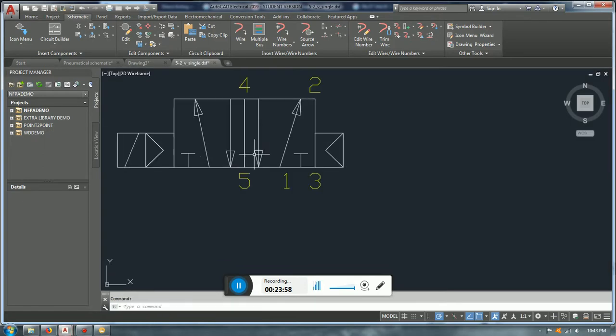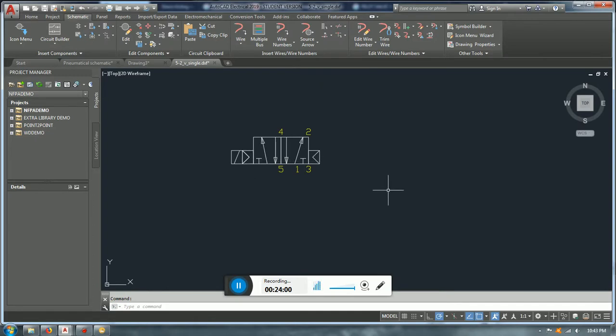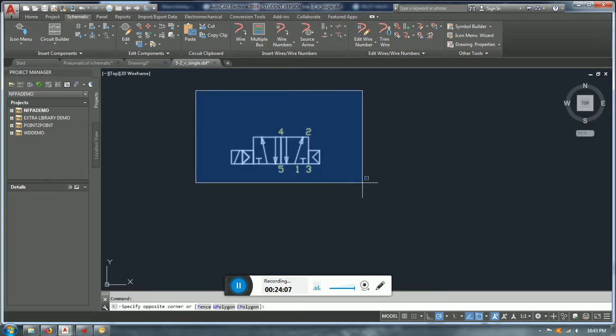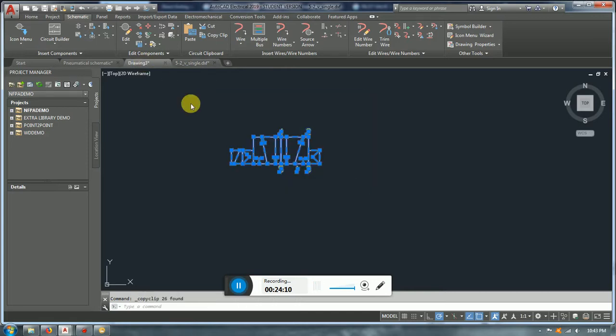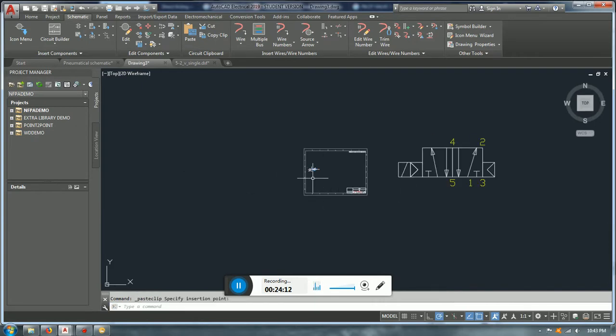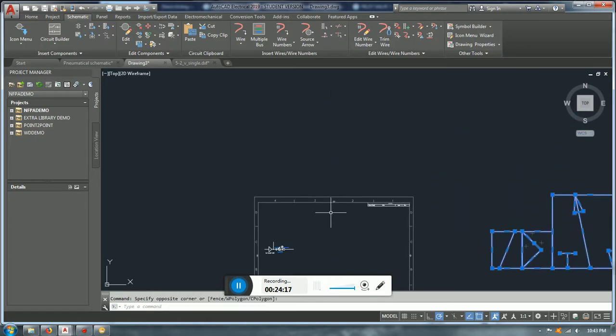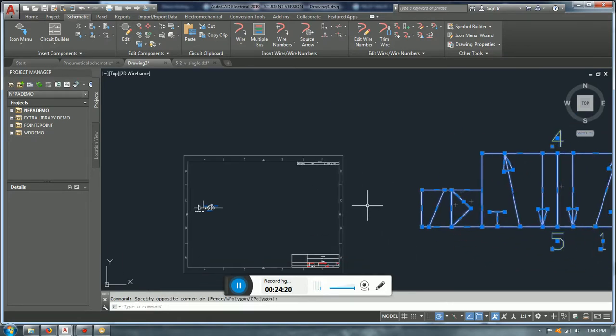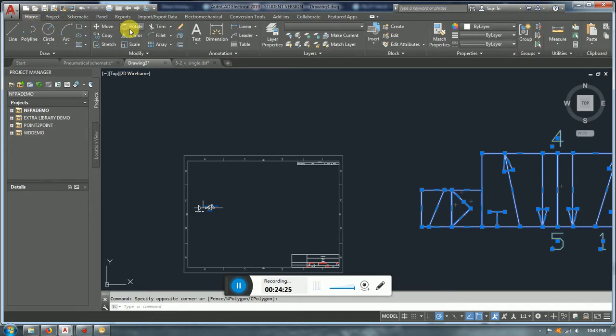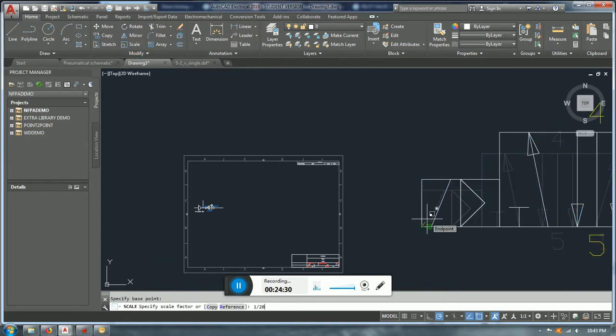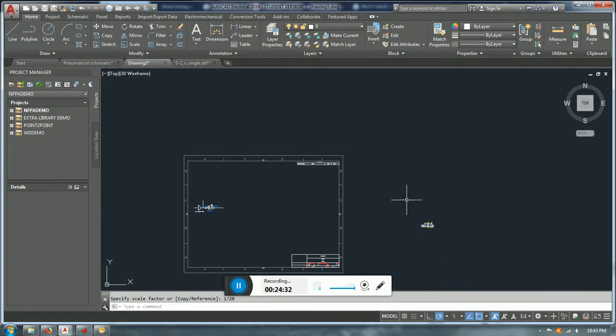These valves don't have that thing of normally open, normally closed, because with both options, they're closed or open depending on how you put that. We're going to copy that. I'm going to paste it here. Problem, you see the scale, it is huge. If I'm not wrong, I think these ones were around 20 the scale or 40 the scale, I forgot. So we're going to do 20 and then see. Whatever scale you're going to do, you're going to have to write it. So 1 divided by 20. Yes, I think it's going to be perfect.